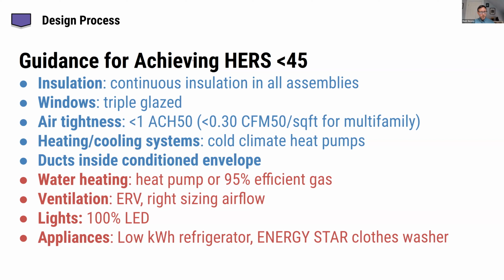And then in things other than the heating and cooling loads, water heating, either a heat pump water heater or a very efficient gas water heater, something like an on-demand gas water heater, although that will kick you into the mixed fuel category in the ERI path.